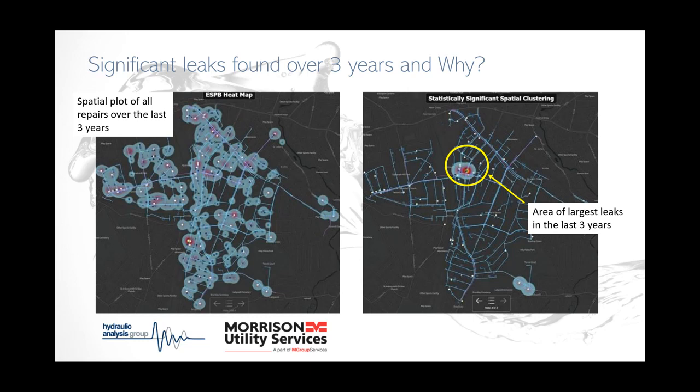And we've now taken steps to actually eliminate this pressure transient. We actually expect now over the next year or so that the leakage levels will really drop quite significantly in this DMA, because we're calming the DMA. We're dealing with the pressure transients. We're solving, getting to the root cause of leaks and bursts, not just finding them.